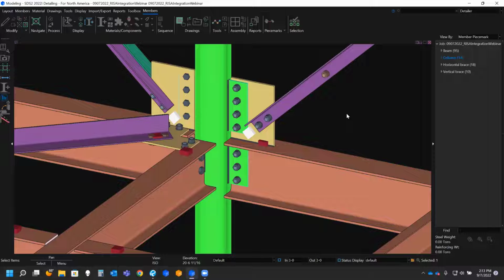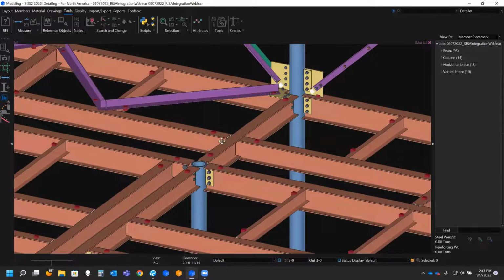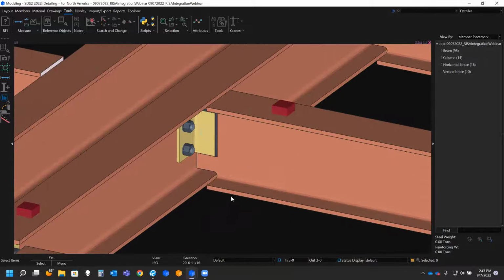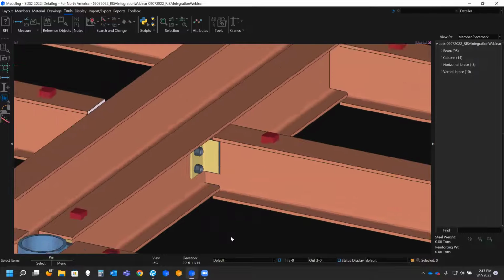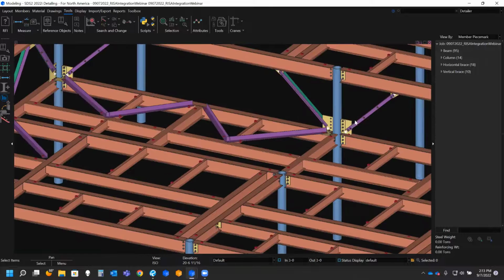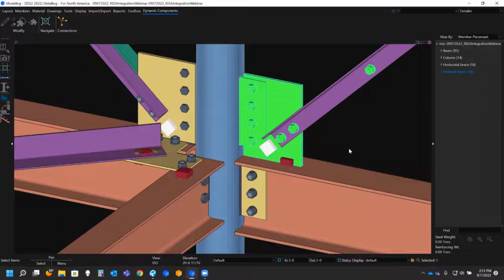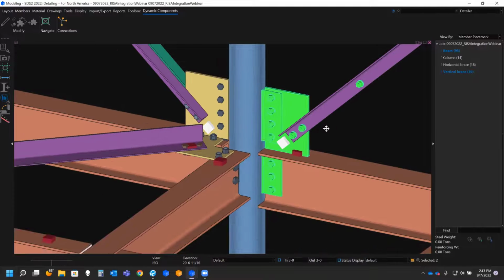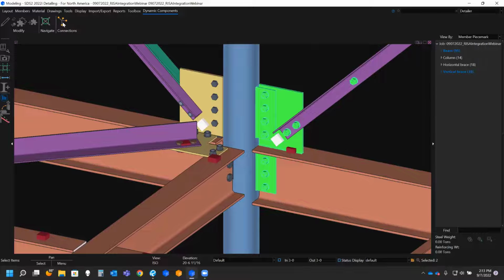We're really looking at that whole joint when we design, to make sure things can be erected. Over here is a good example, a simple form of that. We cope out those beams appropriately based on fabricator settings and AISC checks and whatnot as well. And then over here, we're designing this as one whole joint, one whole node. So we want to be able to document that as one whole joint or one whole node as well.